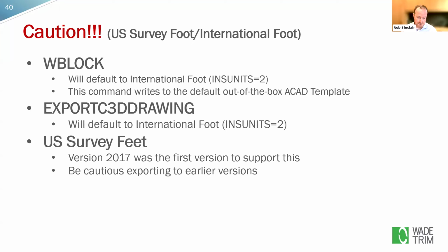Again, US survey foot was introduced in 2017. So if you need to export out to a prior version, it's going to default to INSUNITS of 2, which is international foot.